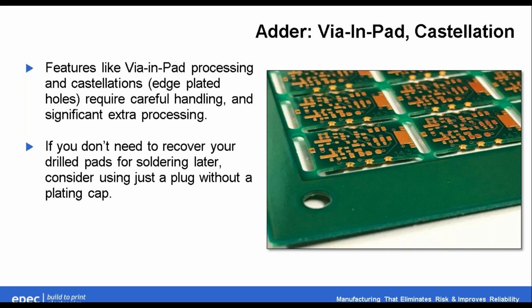And I kind of touched upon this a little bit with multi-layers. A lot of fabricators just have a couple of sizes of multi-layer plates. So they're pretty much hemmed into using raw materials that fit those multi-layer plates. And that's one reason. The other thing too is, even if your fabricator is trimming the material to fit your weird board size, you're probably paying for it anyway. They might not be telling you that. They might be trimming it so they're not wasting plating and so forth throughout the production line, but you're probably paying for it anyway.